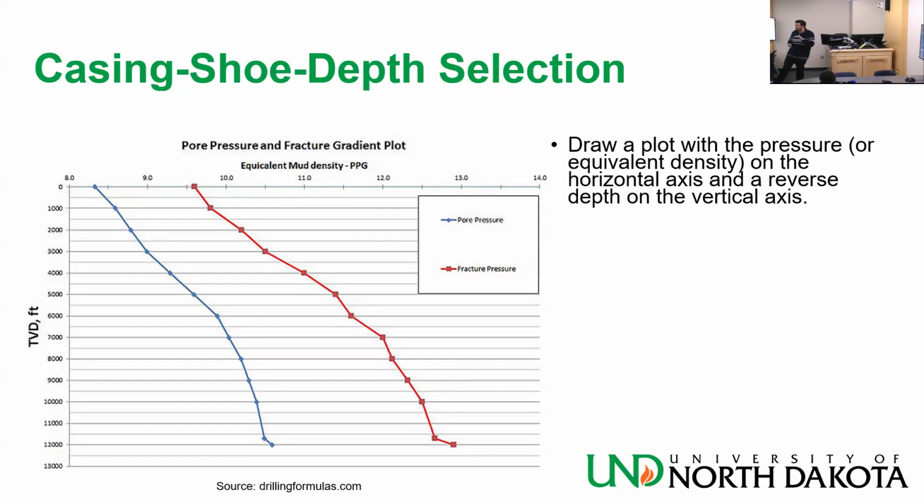Density and depth can be combined to give you pressure, right? To give you the pressure below the mud column. The undergrads who took the class with me know, but I will show you the equation. Every time, and I want you to be very comfortable, if I give you pressure and depth, you can give me density equivalent. If I give you two, you give me the third.